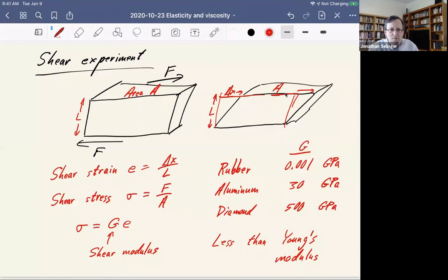For one more example, there is a quantity called Poisson's ratio, which says if you stretch a material, it gets longer, but it also gets thinner in the direction perpendicular to the way that you're stretching. So there's a ratio of how much it gets thinner compared to the amount that it gets longer. So those are 4 elastic properties of materials that I can think of. I'm sure there are more that mechanical engineers have thought of that I can't remember right now.